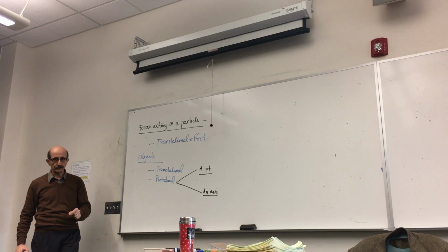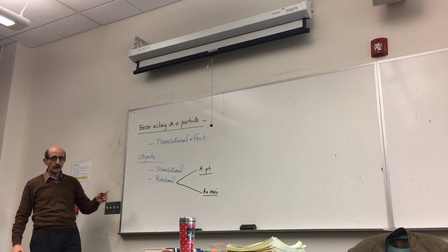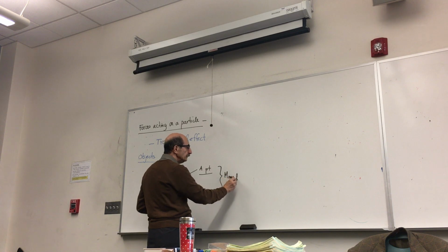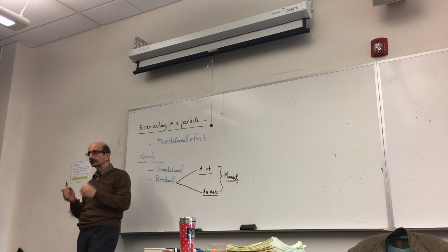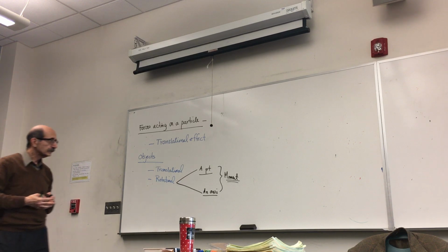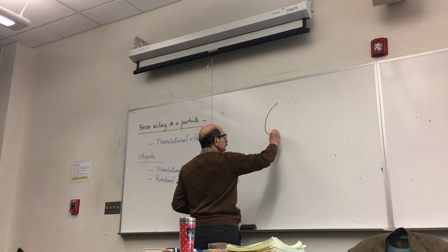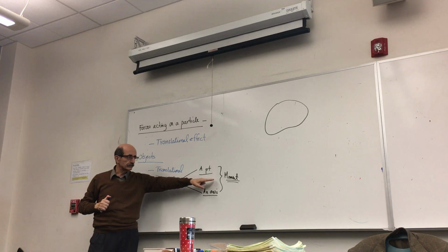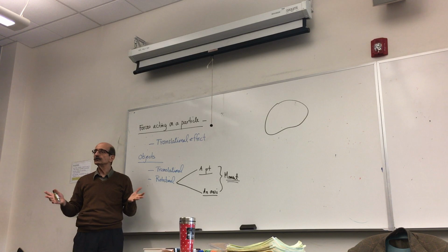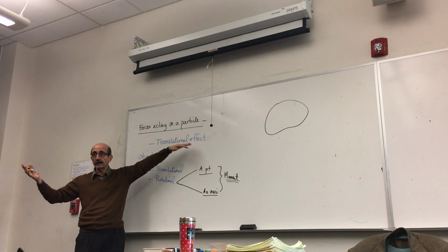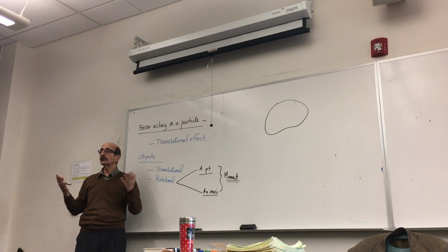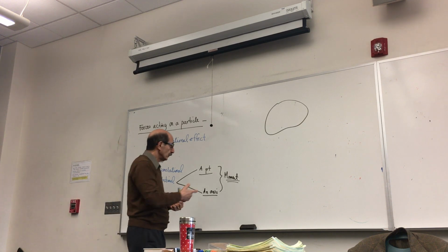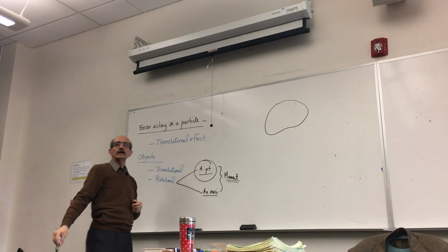The rotational action of a force is described by a quantity which we call the moment. So moment is a quantity that describes the rotational action of a force. How? If you have an object acted upon by a force, and you want to find the rotational action, how do you describe that? In the case of a force, we wrote it as a vector equation. Moment is also a vector, but what kind of a vector is that, and how do we write that vector equation for the moment? First, look at the rotational effect about a point.